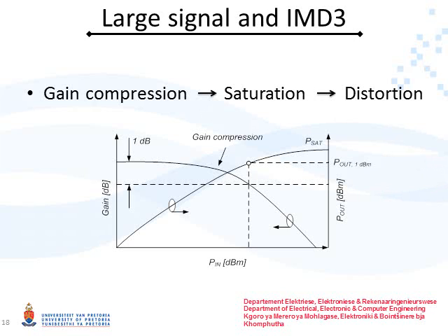However, the main cause of gain compression is the overdriving of the RF signal away from the device's linear region of operation and into the device's ohmic region. The result of this is that the output RF signal is now clipped. Therefore, the gain compression is directly linked to the Q bias point of the transistor. Providing an increasing gain at certain measured output power levels will ensure a constant overall gain, such that the output power remains linear until the saturation limit has been reached, at which point no further linearity improvement can be achieved.